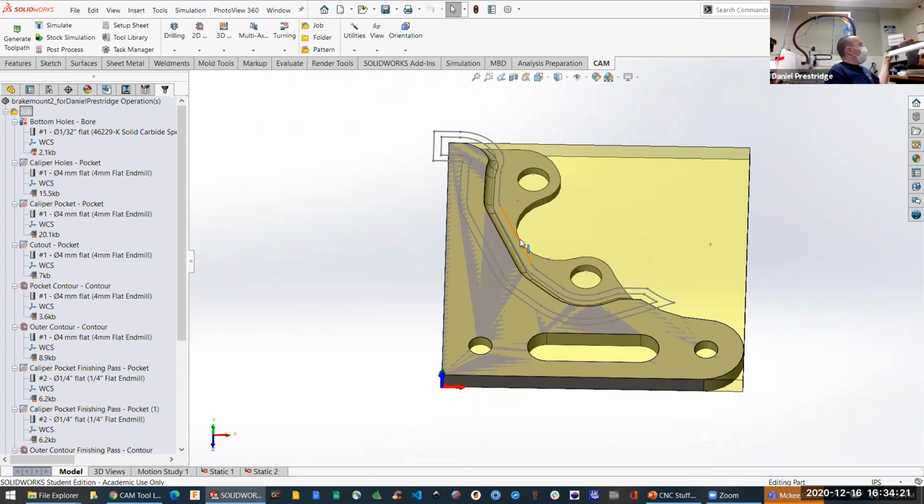And I like to use high density polyethylene as my baseboard, my spoil board, and we'll bolt these down and put something on top, and then drive everything down into it. And you can kind of see some of these indentations and cuts, and that's what it's made for. So you cut these, this sits further down into it, so you can plane this with your end mill. You can clear off that top part, just maybe 0.5 millimeter in total, and you now have a flat surface to work with.